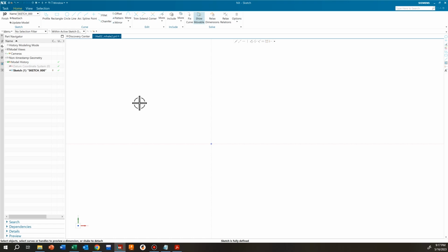And so the sketch that we want to draw is going to define the boundaries of our rectangle or our square. And there's lots of ways to do sketches. There's lots of different reasons to do a sketch a certain way. But these are our 2D entities that allow us to define the boundary of our 3D model. So again, this is 2D. Our drawings are going to be in 2D, and then we create 3D geometry from that 2D drawing.